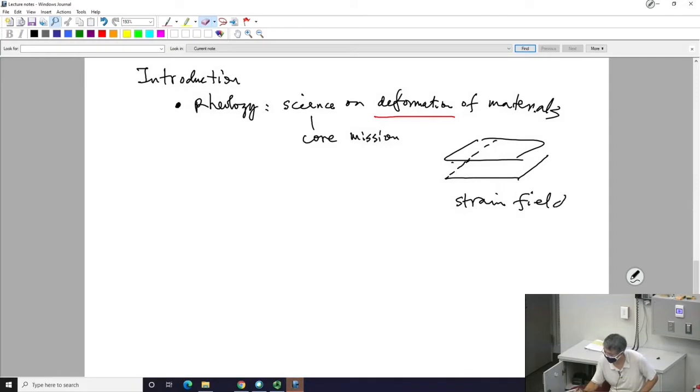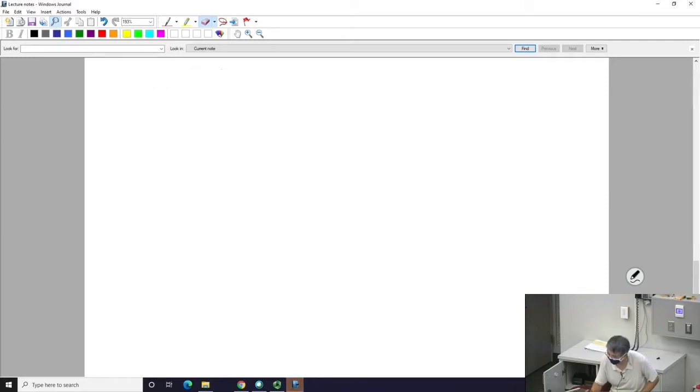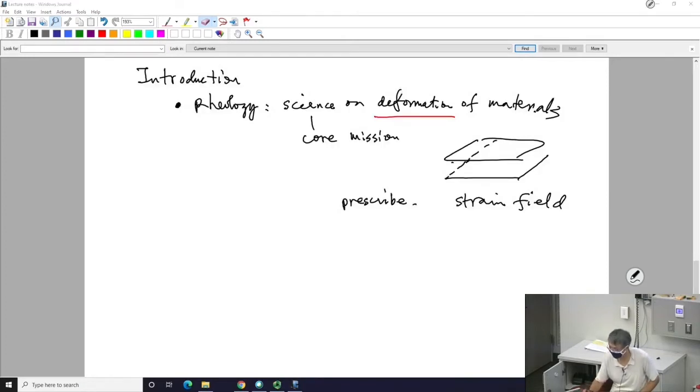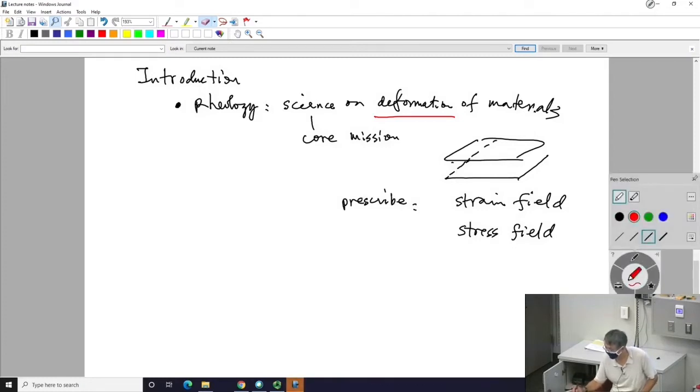When you deal with shape changing, there are really two components to it. Just like in the case of shear, last time we talked about whether the shear is going to obey homogeneous deformation or not. Like my plane moves, then half height moves halfway. So that's the strain field, and as I said, it usually is assumed to be prescribable. What's left is for you just to determine the stress field. That's the traditional view of rheology. This task was assumed to be simplifiable to dealing with the stress, because the strain field is already known.